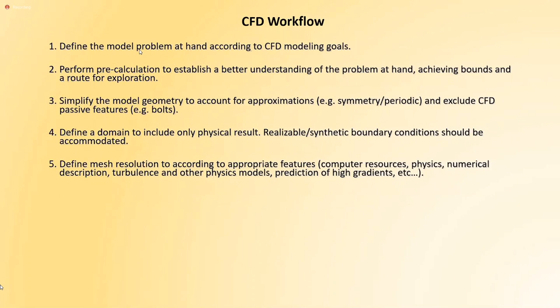A CFD workflow usually works like this. You define the model problem at hand according to CFD modeling goals. You perform a pre-calculation to establish a better understanding of the phenomenology, achieving bounds, a route for exploration. This means that we usually don't go and simulate without thinking before that.